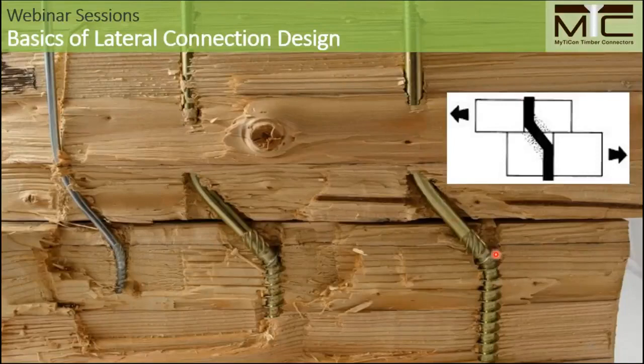If we want to use the root diameter or the shank diameter here, of course, we always want to use the most conservative case, and the NDS gives us directions. If this root diameter is far enough from the shear plane, so yielding does not happen in the root section of the fastener, we can actually use the larger diameter.